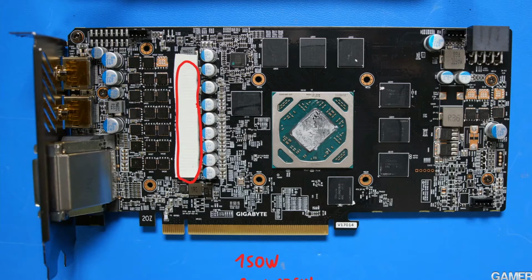And this also explains why the RX 570 has a 150 watt TDP, but if you're in the system, you see you have a limit of 90 or 125 watts, for example. That's because an AMD card only sees the power that's going into the V-Core VRM. You still have VDDCI, you have VMEM, and then everything else, like there's a PEX rail, I think. Yeah, that should be the PEX rail. And then fans consume power, all the display drive stuff consumes power, all the ICs consume power. There's a lot of things on the card that consume power other than the core.